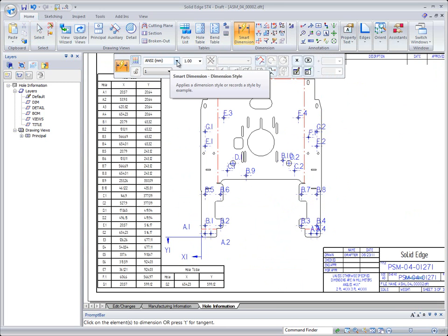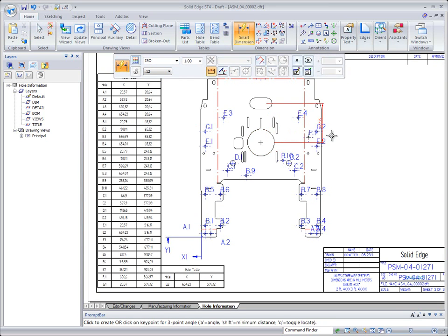And now I'm going to go in, and we've been working in kind of an ANSI type drawing, and here for this particular sheet I want to say I need to detail this sheet in an ISO standard. So we'll just drag off a couple of different radial dimensions plus this linear type dimension.